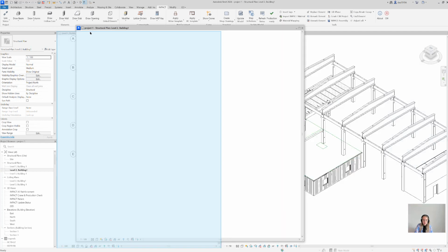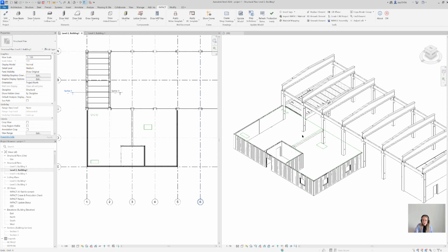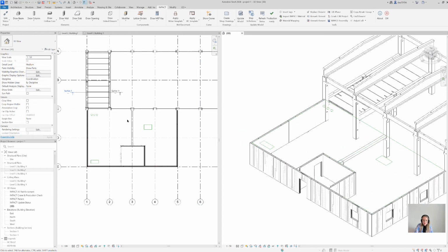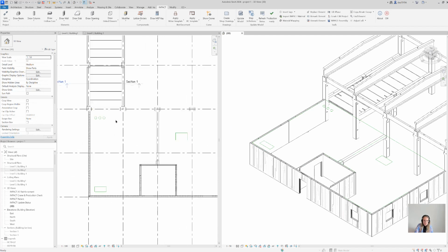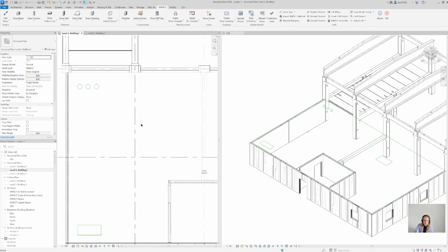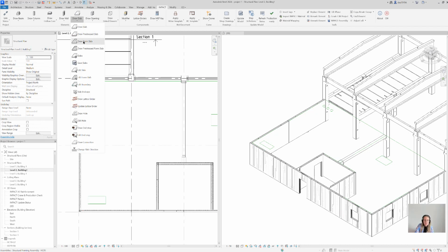If I move it on the left side. Okay, we can see what's going on here in the 3D view. I've already drawn some modular lines, which I hope are going to help me do the form slab, and I'm going to activate the draw form slab command.